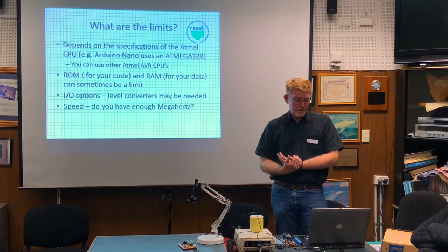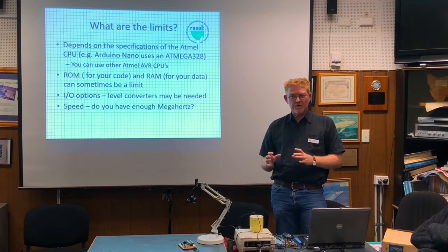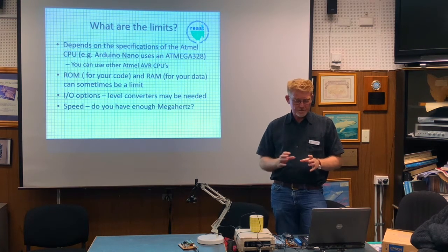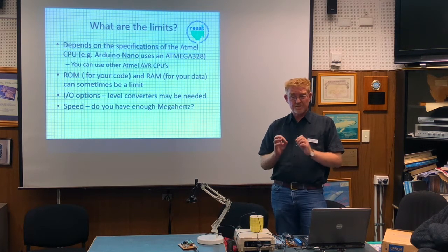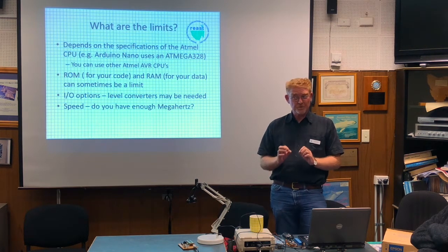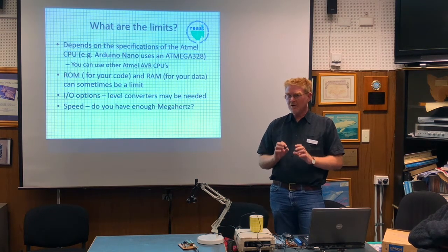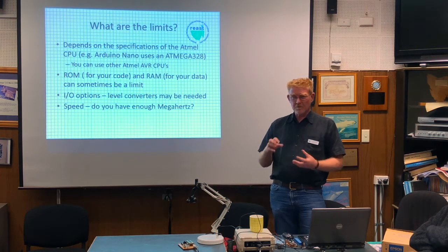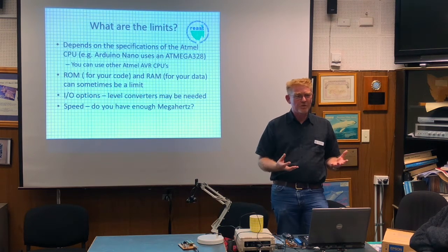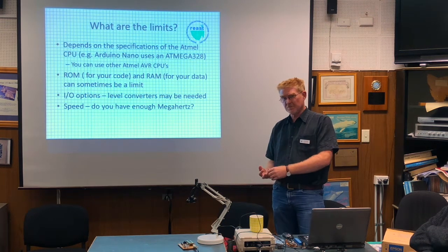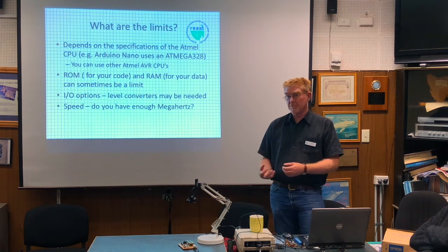Limits. These are small devices. Part of the giveaway is you should look at some of the part names in here. For instance, the Atmega 328 has 32 kilobytes of memory for storing your program. It's kilobytes, not megabytes. Now, that can be quite a lot if you're working in assembler or very small programs, but you're not going to run a word processor or a web browser or talk to the internet with that amount of capacity on chip.